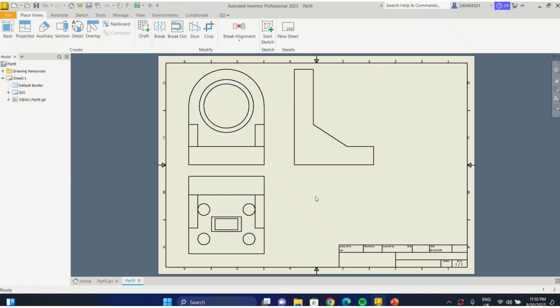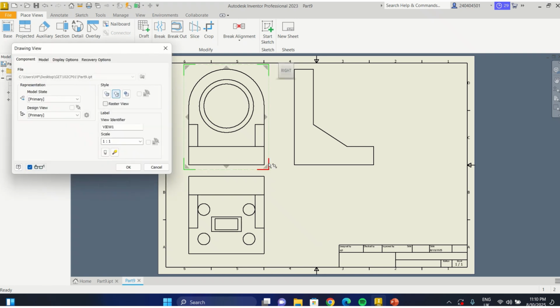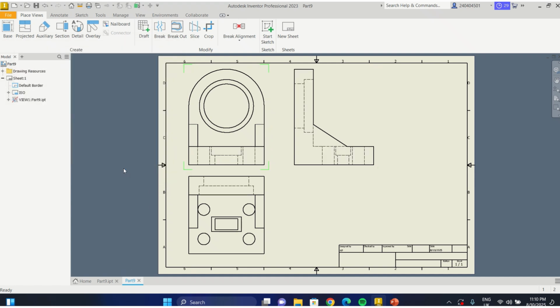In that case, this is what you are going to see. So the hidden details are not shown here, and that is not giving you the correct views as seen in the diagram. So you have to come back to this place. If you come back to this place, you click on the first icon here. It's showing you hidden line. That gives you the hidden line. Then also click on raster fill, and then you can okay. So all the hidden details are shown clearly to you.